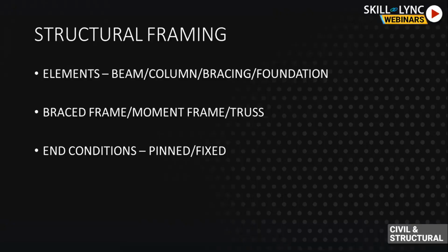If the foundation rests on the soil, based on the support condition of the foundation, we call it fixed. It is supported, and it can transfer the forces, the moments, everything. A pinned support cannot transfer any kind of moment. It can only transfer forces, not moments. And a fixed support can transfer any kind of forces as well as moment.